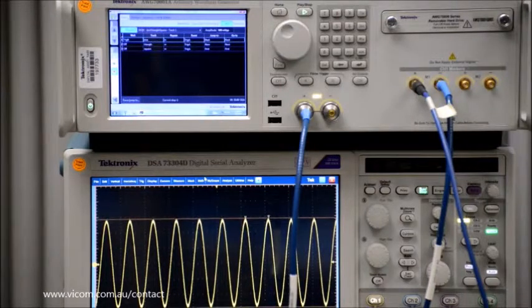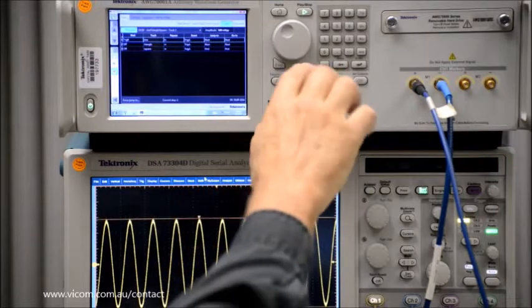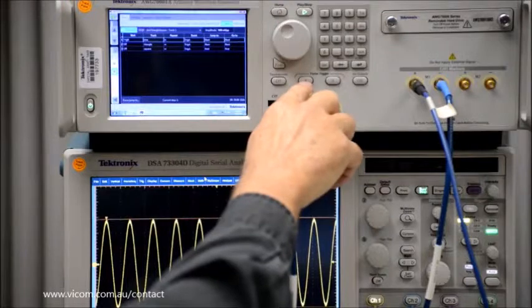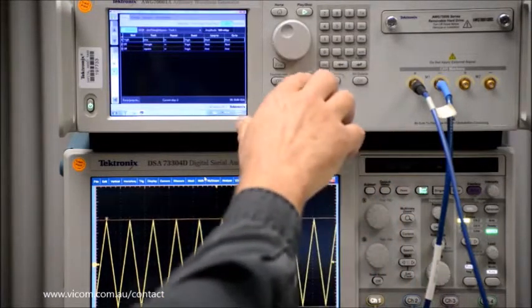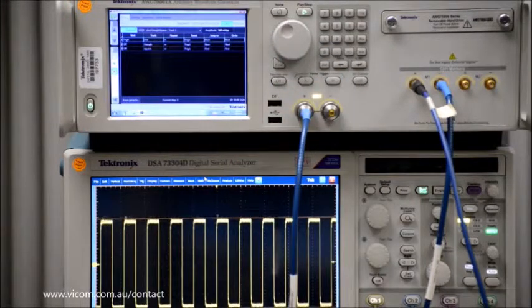As we mentioned before, it's repeating infinitely until we get another event. I've set this event to go to the next waveform, and this is set up for trigger A, so I'm just going to push the trigger A force trigger button, and you see now we go to the triangle, and again it's set for infinite, so it's going to continue to play this waveform infinitely. And then if I hit the A button again, you can see that it goes to the square wave. So again, it's a very simple concept. It allows you to go through many waveforms.